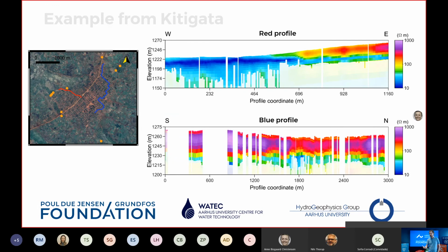And so this is giving you some evidence that if you were to drill a borehole to, say, in this case, 45 or 50 meters, it's very likely that you're going to intercept an unconfined aquifer system that's sourcing the springs that the town is already reliant on at the edge of the town or at the edge of the community. But that's just one example of how these TTEM surveys can guide potential future drilling efforts.